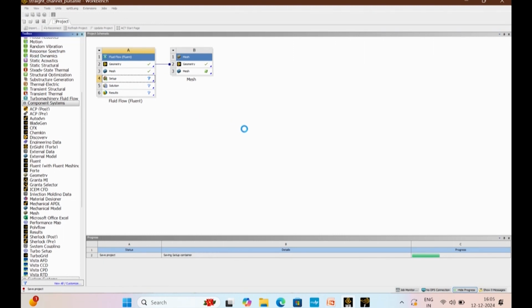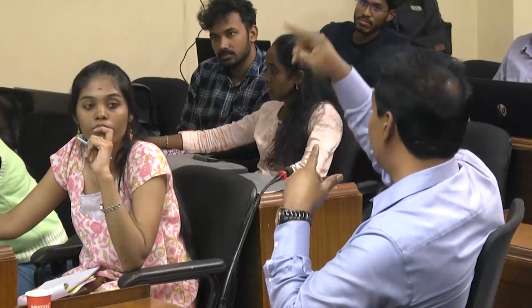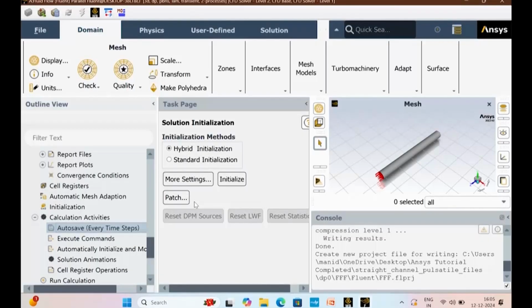So I am just saving it before starting the simulation. You have to be very careful when you choose this one, because once your simulation is done, if you need some intermediate data, you have to run it again. So based on the profile, check which data you need for the explanation. Maybe the peak one, couple of peaks, couple of bottom, and then choose the time and set up that time I need a data.